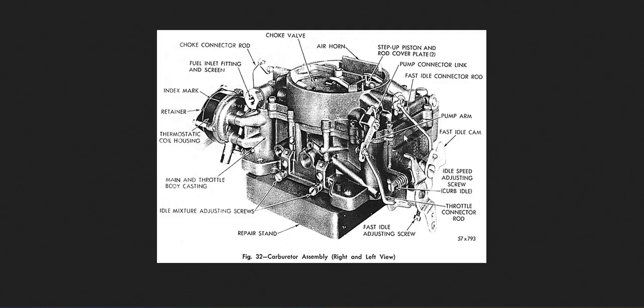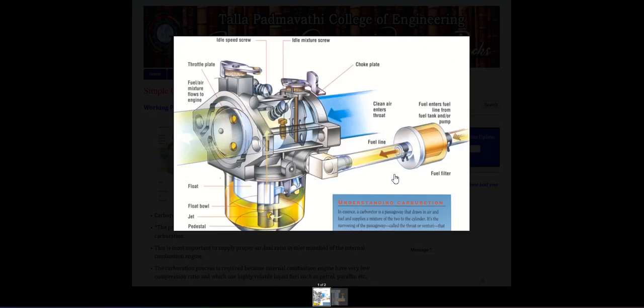Most of these blocks are made from aluminium. I think that I have another example here to show you that this is for the two-stroke internal combustion engine. Most of the parts here are going to be casted individually, then they're going to be machined, and they're going to be assembled with the other parts to have the complete